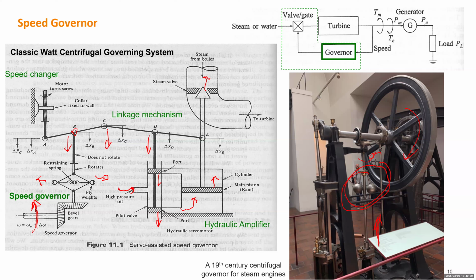Then for that function, you can draw the Bode diagram. For some studies, if your research focuses on optimization of the turbine or generator in a power plant, you can keep this accurate model. But if you want to provide a model to engineers for power system stability study, they don't need this 200 or 300 order system. They can use a Bode diagram to simplify the model, similar to the frequency response. When we draw the Bode diagram based on how many time constants you want to consider, you can use it to fit the transfer function and get a simplified model.